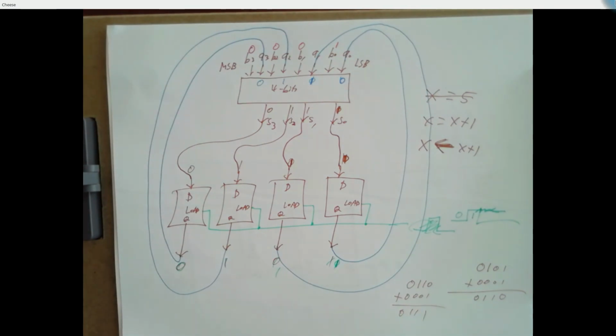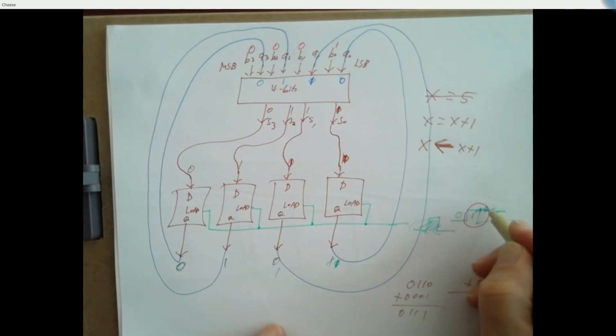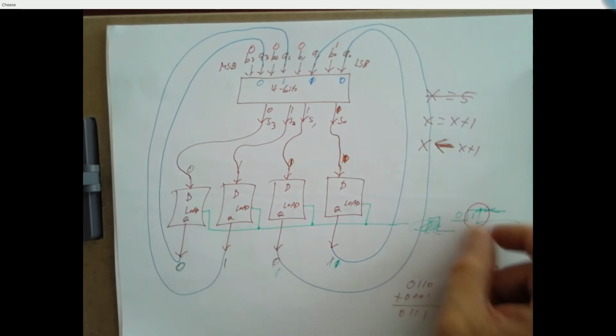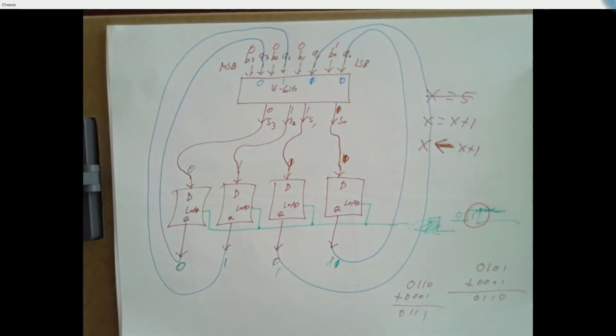But the timing of this becomes critical now. Because if we don't leave that load line high for long enough, if we only raise it for 1/10 of a nanosecond, the circuitry inside here probably doesn't have enough time to stabilize, and we can get goofy results. But if we leave it open for 5 minutes, we're going to get a bunch of values coming through, right? Every 20, 30 nanoseconds, we're going to get a new value loaded into here.